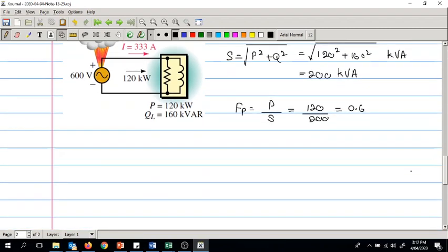right? So if we want the power factor to be corrected to 0.9 instead of 1, right? Earlier what we considered was 1, because in the general case we don't expect it to be 100% corrected, because there can be different loads connected at different times and things like that. And cost-wise, achieving 100% or unity power factor correction is costlier than achieving up to about 90-95%. So let's consider the case that we want to achieve 0.9 power factor.